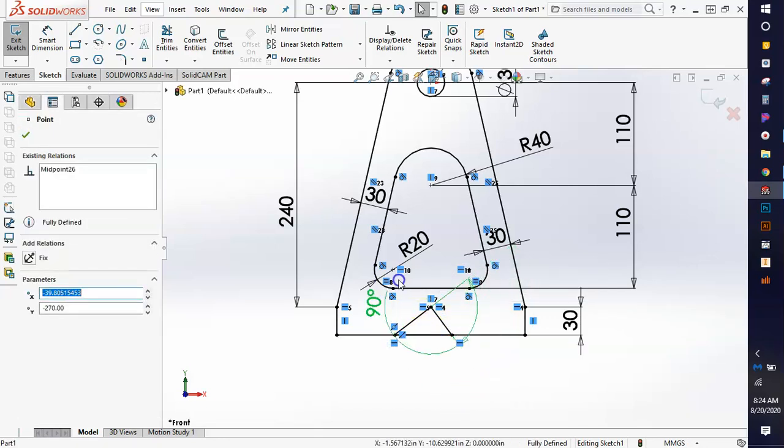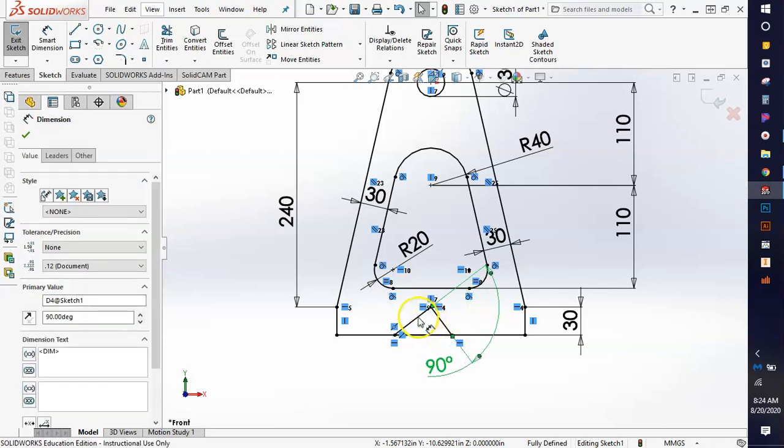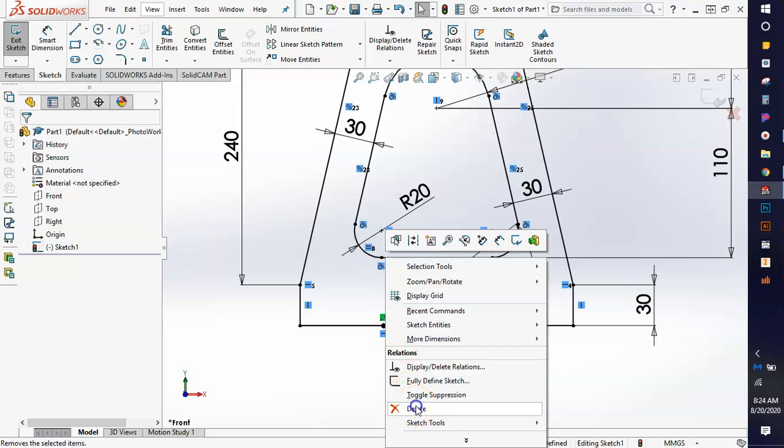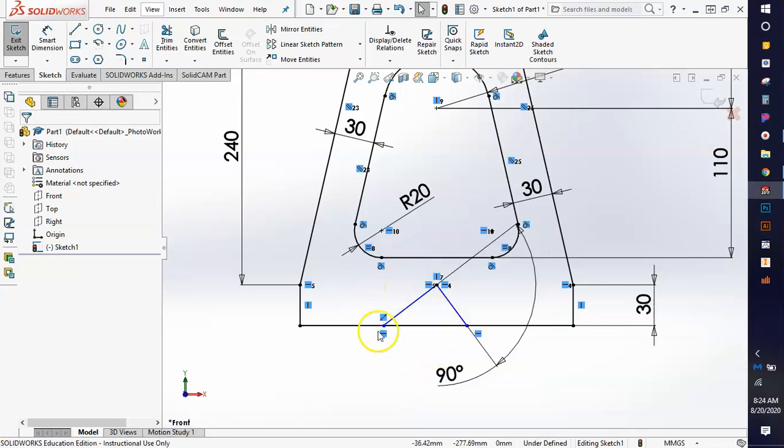So it actually looks like somehow it flip-flopped my triangle. So you notice this bottom line is over too far. Okay, so if yours does something strange like this, you have to look at some of your relations. And what you'll notice is maybe your computer will do this. Mine kind of just took that line and connected to the midpoint of this line, which is very strange. I didn't do that. So I'm just going to delete that relation. Now, if you can't figure that out down here, what you could do is simply just delete all of these little lines and redimension them and re-put them in.